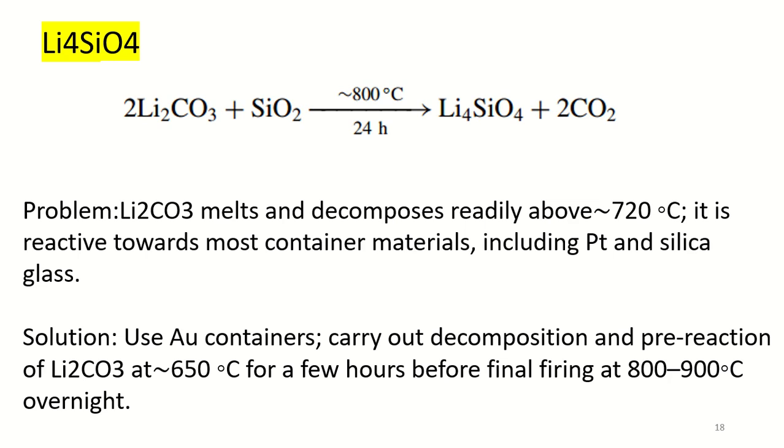The optimum temperature for this is about 650 degrees Celsius, and we should make a pre-reaction at this temperature before the final firing, which is 800 to 900 degrees Celsius.